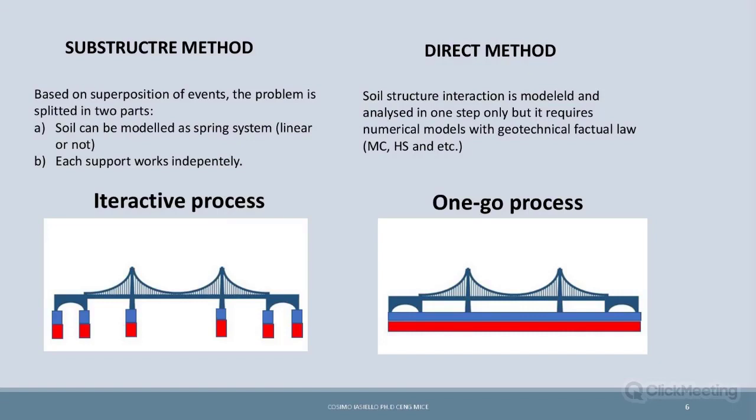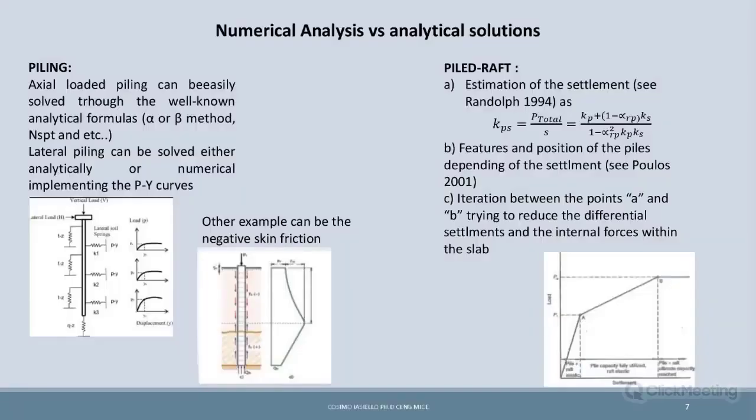And then we have the direct method. This direct method is what geotechnical engineers are familiar with. The soil is modeled as a continuum. In Midas it is a solid, and this can be used efficiently for both civil works or buildings, whatever design we have.